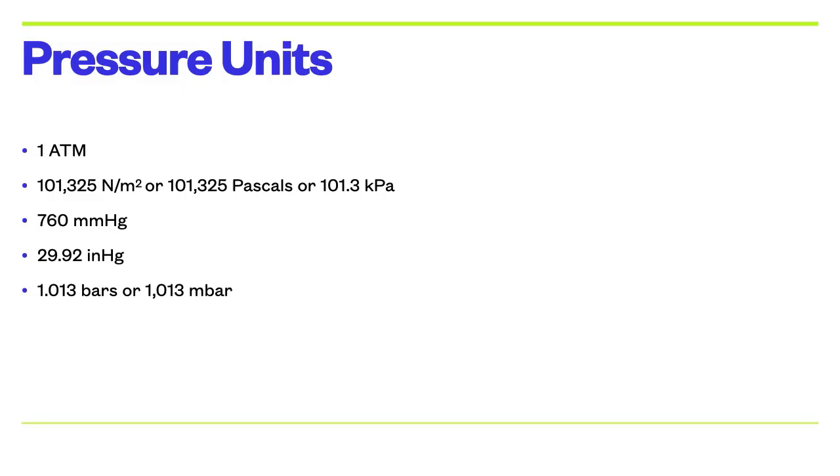Finally, when measuring fairly low pressures of things, like measuring the pressure of gas in a gas line, or the amount of vacuum pressure produced by an engine when it's running, sometimes you hear those measured in terms of inches of water, because the manometer which is used to measure them has water in it.